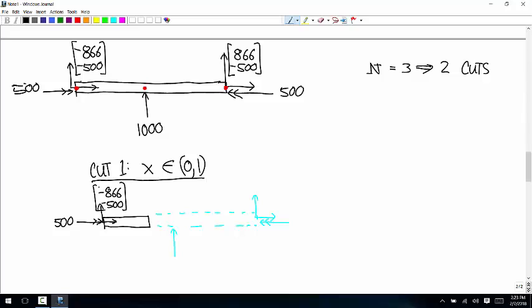And the only other place that the surroundings make contact with the boundary of what we've isolated is at the attachment between the metal that we've isolated and the metal that we're ignoring. And so those are the internal loads. So that's going to be a tension T, a shear force V, a bending moment M about the z-axis, and a torque, fancy T.